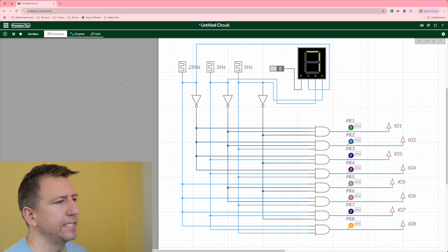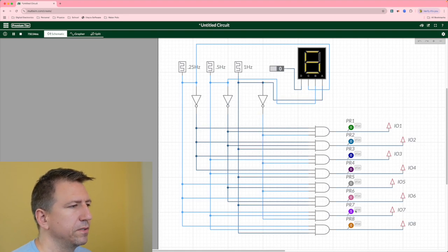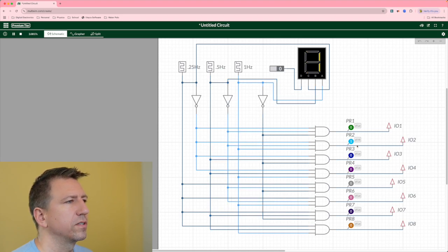And then you can see as we're going through, min-term 6, and then 5, min-term 4, min-term 3, min-term 2 coming up, so on and so forth. This makes sense that it's counting because I set it up to do a count. And so we can see that only 1 is active at a time, and it's representing the output line that corresponds to the min-term number.